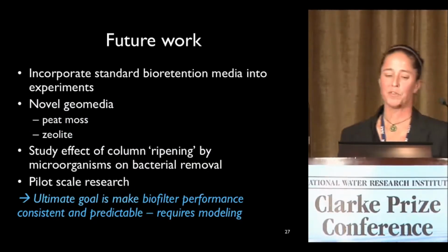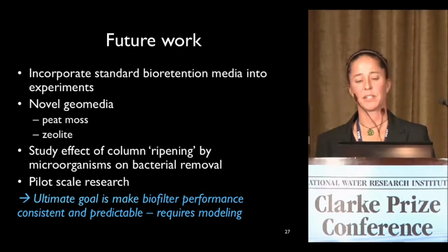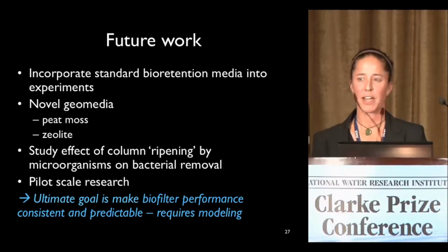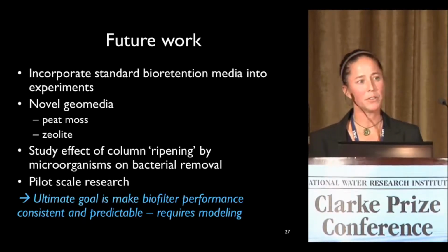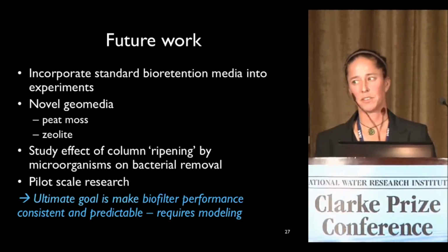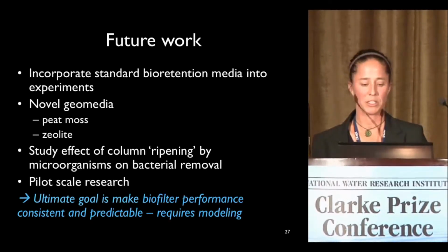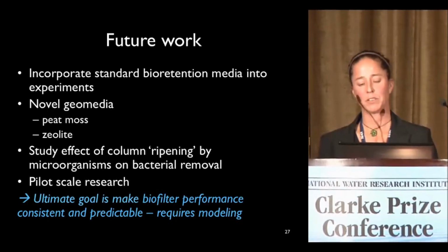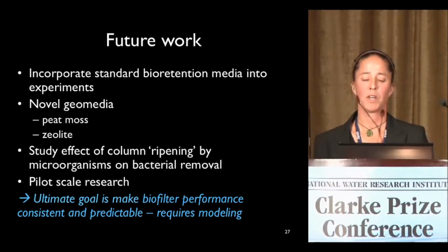Okay, so future work, I mentioned already some of these things, incorporating standard bioretention media into the experiments. In talking with Geosyntec, they've been using things like peat moss and zeolite in their biofiltration systems because they're very good at removing metals. And so it would be interesting to see how well these perform for removing bacteria. We're working right now on studying what happens when you actually ripen these columns by having microorganisms that are present in stormwater actually start growing in them.